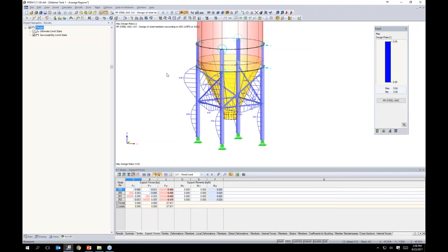Realistically, I know I flew through that, and the point being that I do have a previous webinar, once again, as I mentioned, dedicated to only AISC design, where I go into much more detail. But it's nice to know that you can design an entire industrial structure within one model. So you can design these steel elements according to a stress ratio, but we can also get design of members per the AISC, for concrete ACI, if we ever have any aluminum members, and so forth.